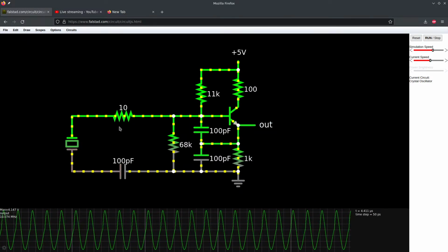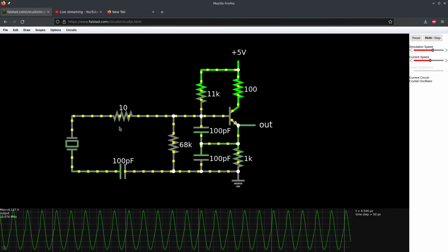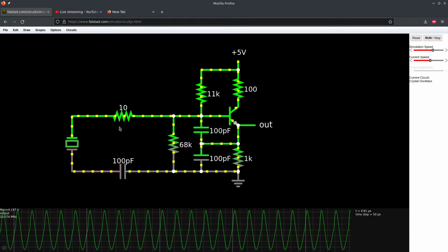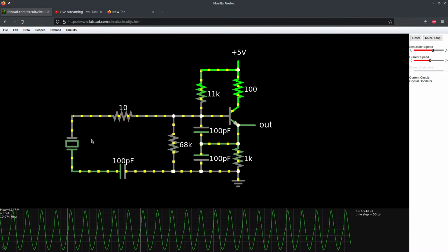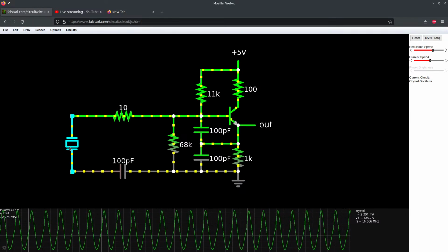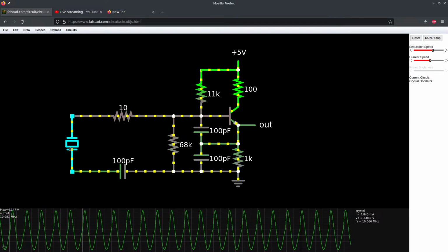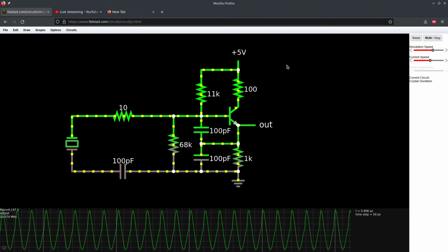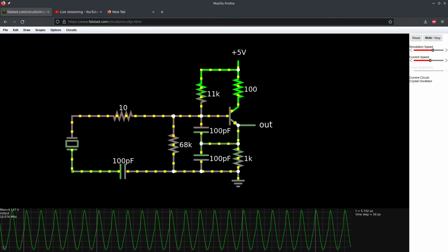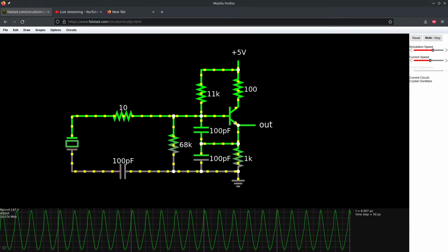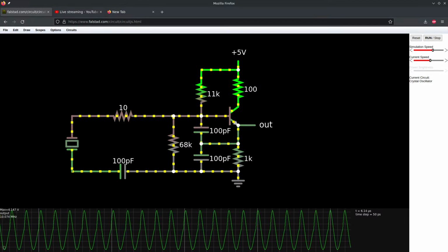It's an analog circuit. It's not something you need to concern yourself with how it works, but that's what it's using it for in there. Okay. Ultimately, it's going to boil down to we have a crystal that we're going to attach to our microcontroller, and then it needs 2 loading capacitors on it, which are specified with the crystal. So as soon as I find where they put the crystal in this, I'm going to pick one the same size as the people already figured it out.